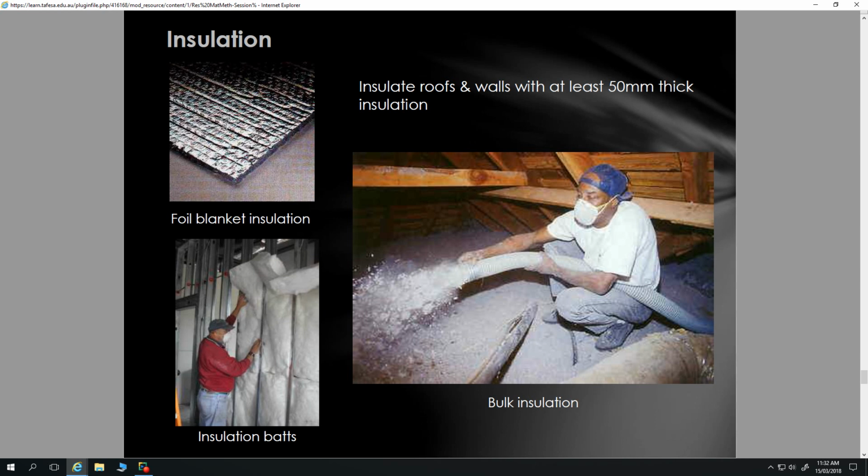That's thermoset foam with a layer of plasterboard on that, so it's in several layers like this. That goes on the underside, and then we put in our insulated sarking up there, 0.5 for that. Got a total R value of 5 for the system at the end. So it can be very handy in that sort of scenario if you want to achieve a raked ceiling but have that insulation there.